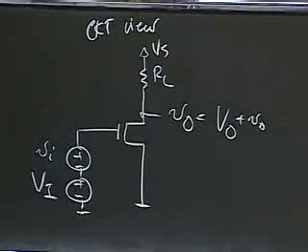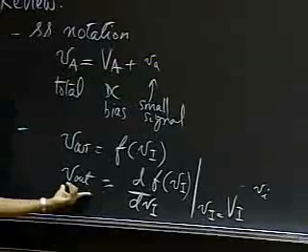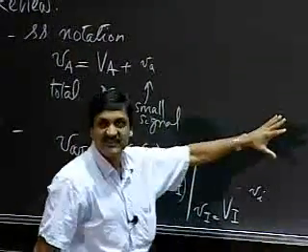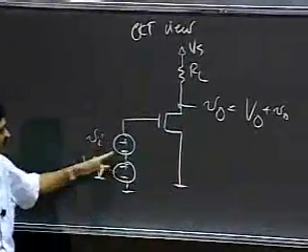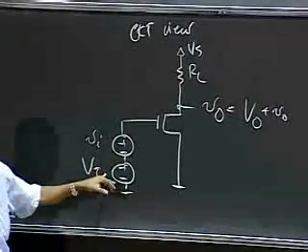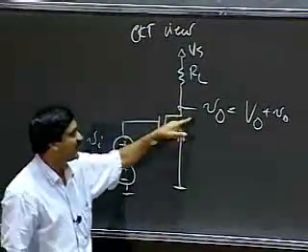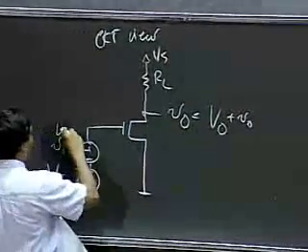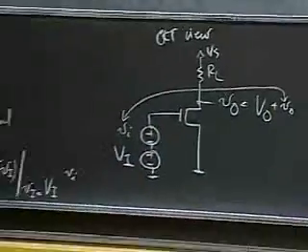So what we've done here is mathematically computed small v out. And what I'm showing you here is to get the same effect in a circuit, you build your circuit and replace what used to be a total variable with a DC bias plus a small change. And then you'll get your output here. And this output will relate to this input using this expression.